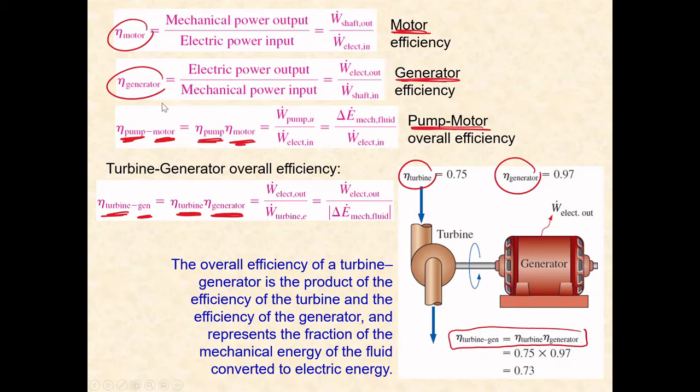All right, so you know that there is a series of processes. For example, if you use a pump, first you must have electricity, and then the electricity must cause the shaft to move, and then the energy from the shaft will be given to the fluid through the pump, right? Or if it's a fan, it's also through the fan, right? So you go through two processes. You go through the motor that converts the electricity to shaft work, and then you go through the pump, which converts the shaft work from the pump to the water. So it means it provides the energy to the water, right?